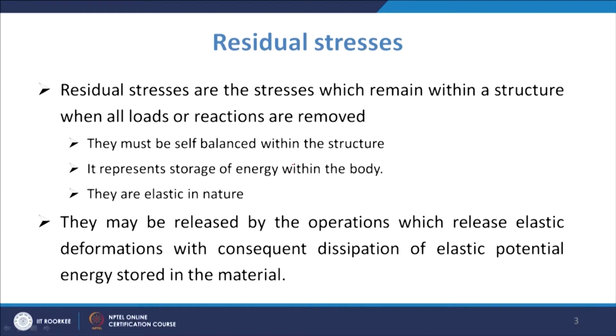So, what happens when by some means you try to remove these stresses, it will go to a different state. Suppose you subject the specimen to some heat treatment, say annealing. It will come to a different equilibrium state, and a new static equilibrium will be established when you remove those external means.